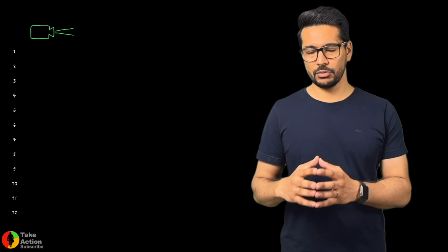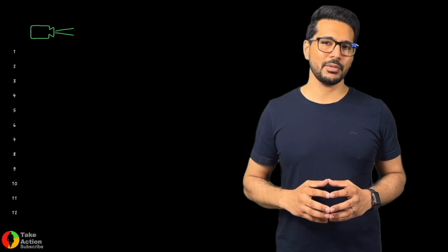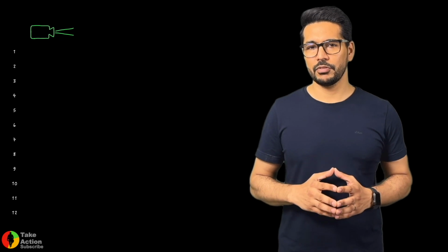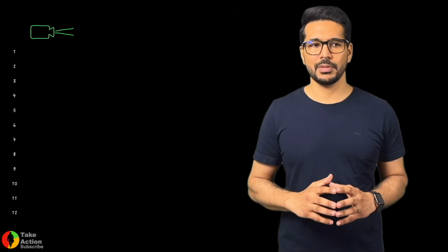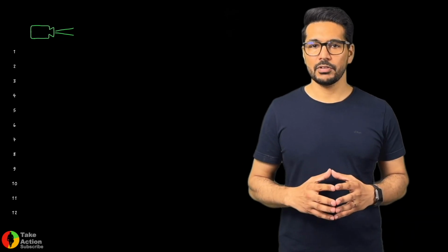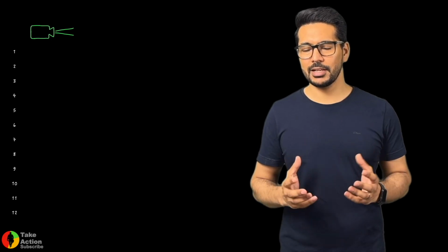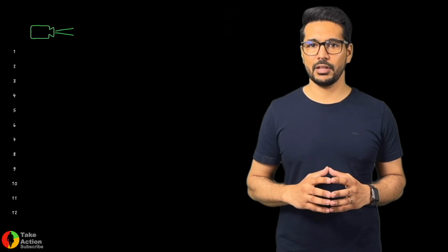The very first step is to record all the activities being performed during this preventive maintenance. There are 2 methods. First is that we go into the production and we note down all the activities being done. The second method is to do video recording, which makes every step in this analysis very easy and very effective.